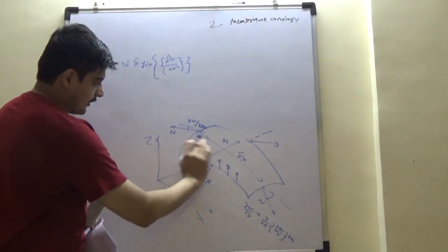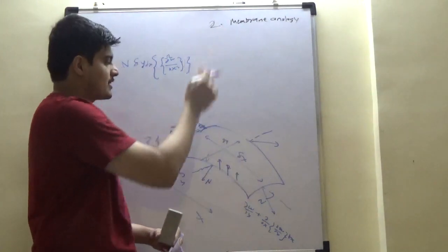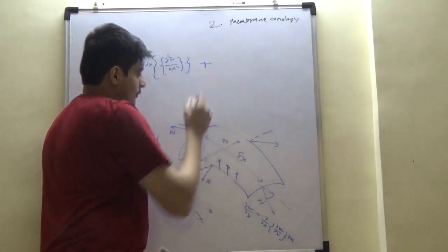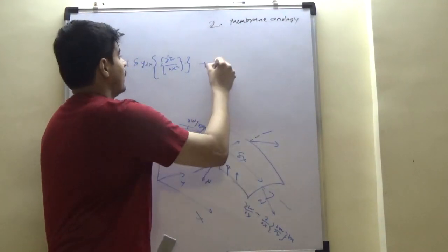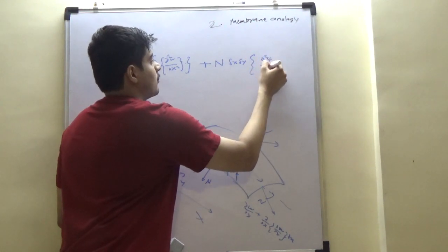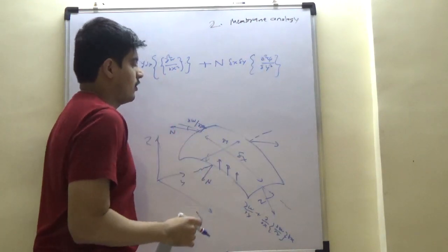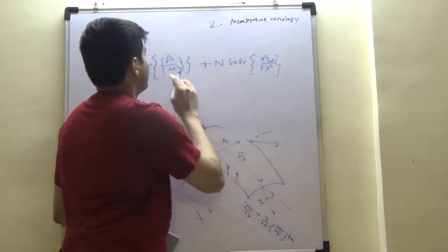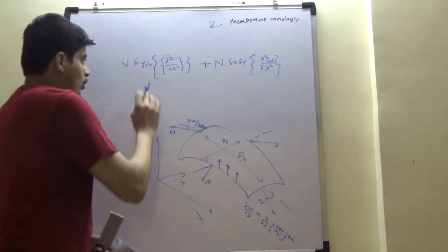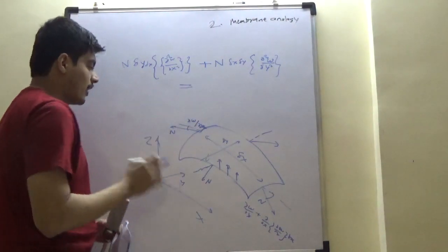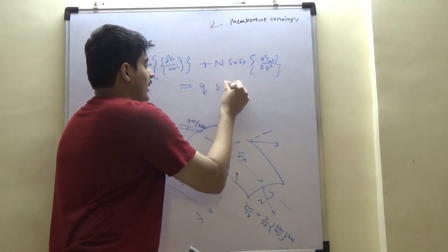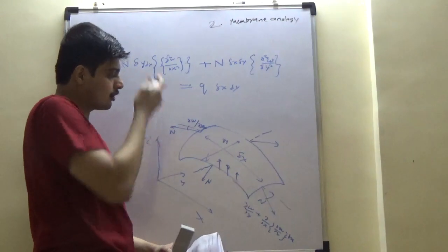So the double gradient of this displacement in Z is going to play a role. The second component, by the same reasoning, can be said to be del square W by del Y square, and delta X delta Y is again the normal. Both of these have to together resist the load Q delta X delta Y, because these are the summation of the force.